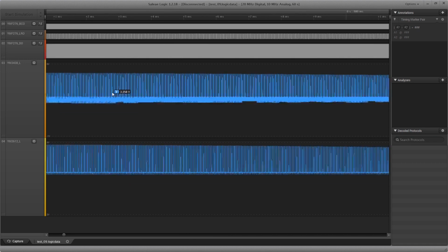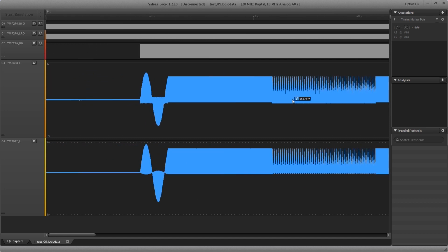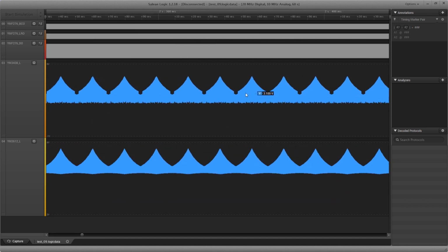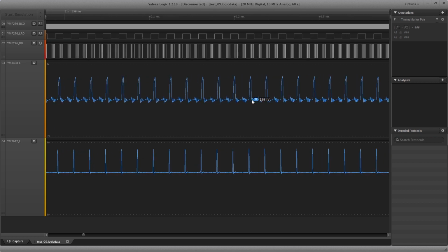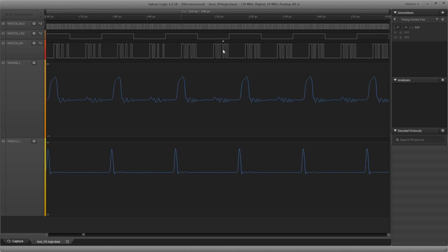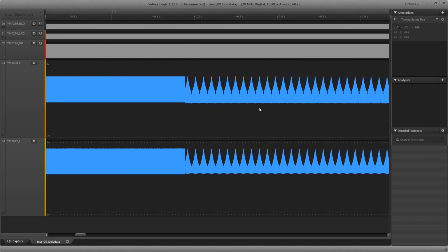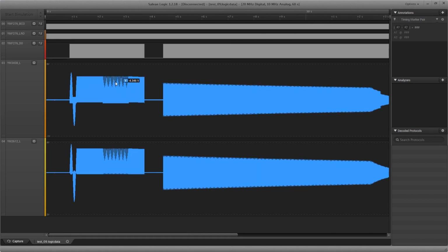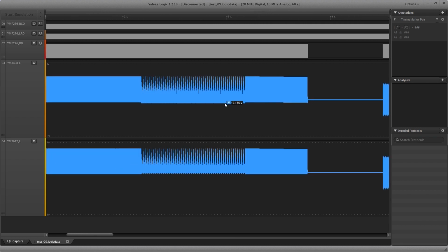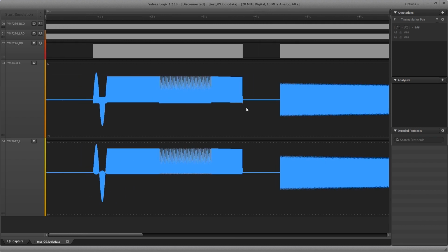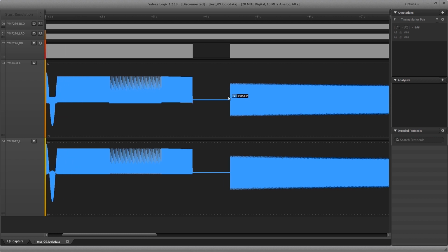The weird signal at the start is actually some clever form of synchronization trick. The internal counters of the OPN2 for the LFOs and the EGs are free running, so instead of trying to force resync them, we just try to figure out which state they are in by doing this little pattern there, and we figure out exactly the cycle they are at, and we apply those values directly to our emulation counters for them to match.